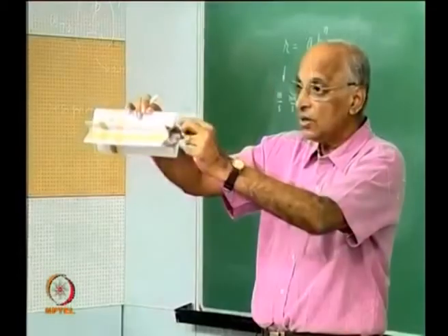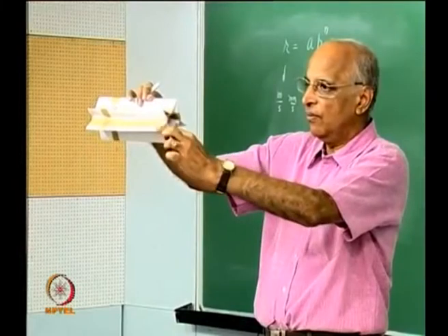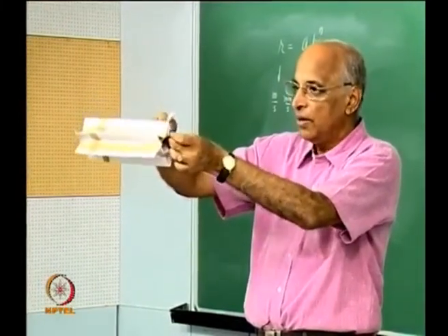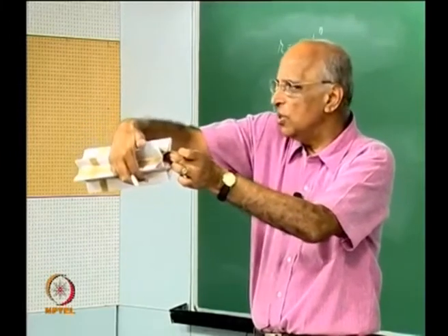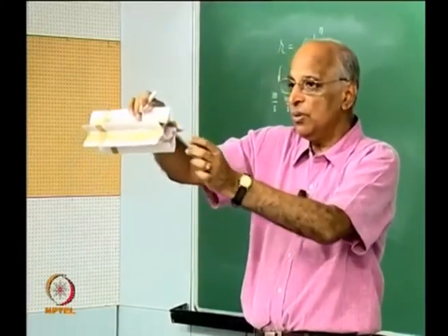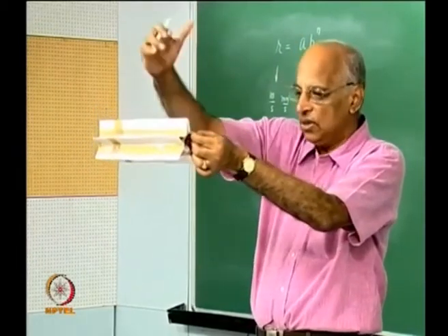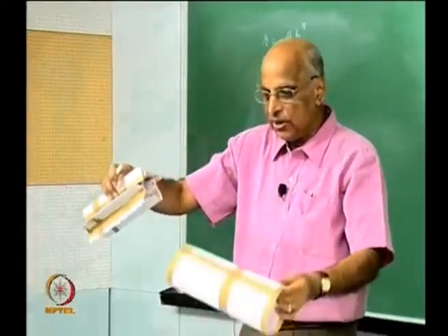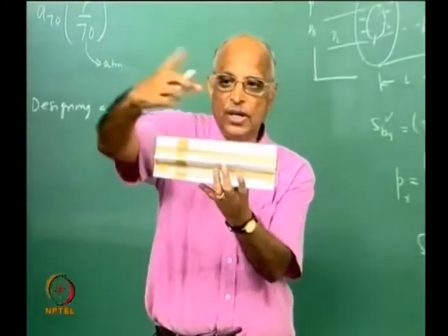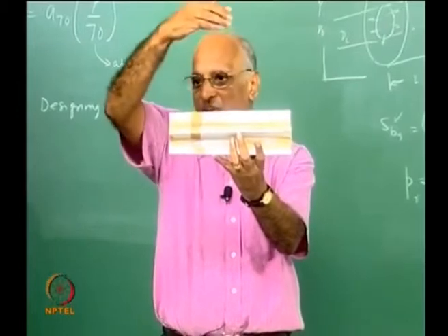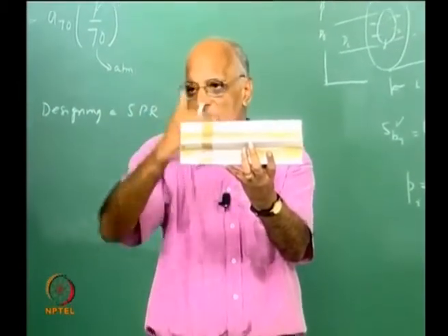Now I find, well, the star, this is something like a 5 vertex star, and therefore now I find my surface area has increased enormously, and therefore now I must be able to evaluate how the burning surface will evolve as it continues to burn. In other words, this is my outer diameter, the outer diameter will come over here and the burning surface will evolve along these surfaces, and this is the problem which we must do.